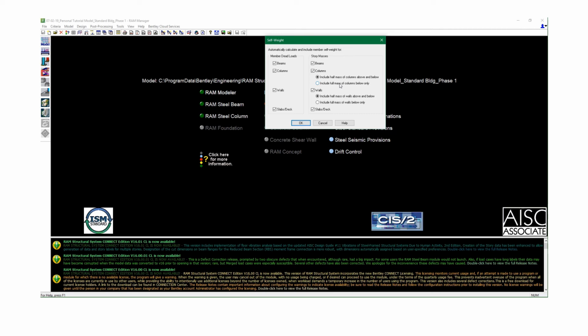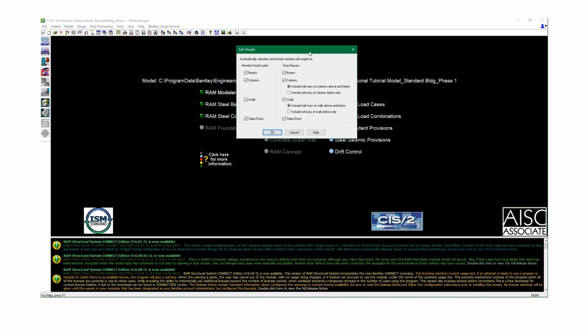If that's soft soils or liquefiable soils or anything like that, you're in a whole different ballgame, and you should include all of the mass, right? And in order to make sure your structure is stable, you may want to include your foundation in the analysis in that instance too, to include the P delta effects from the sway of the foundation just as well.